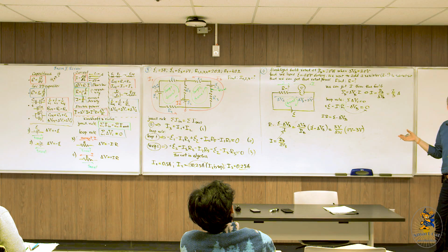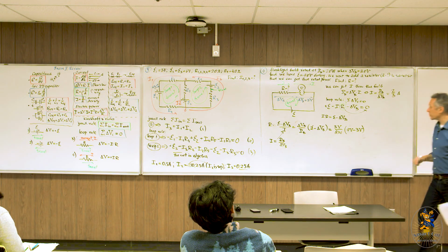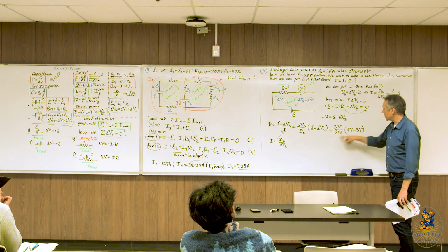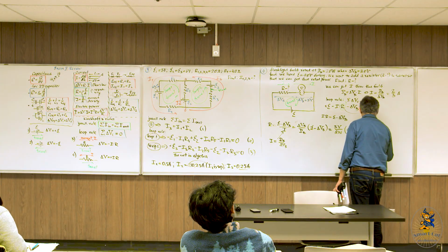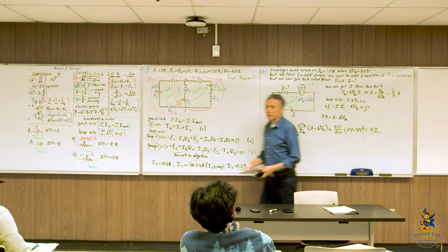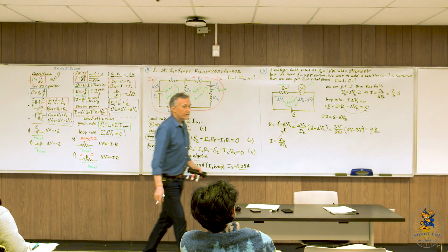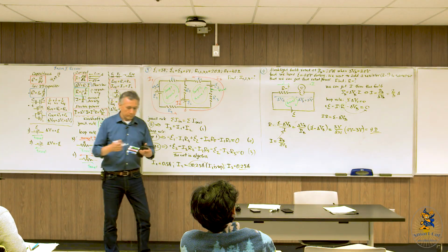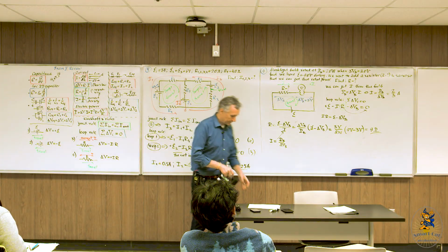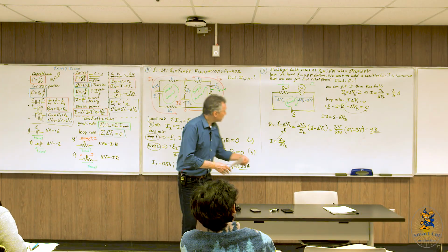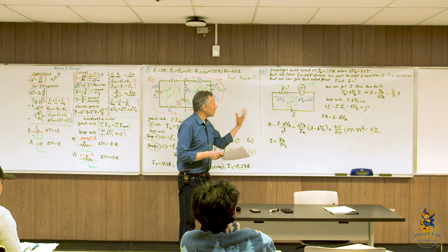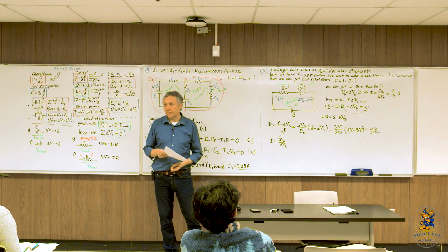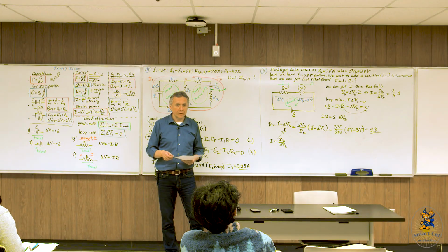It will be 9 ohms, 9 ohm resistor, right? So the 6, 3 times 3, 9. 9 ohm resistor. So you need to connect in series 9 ohm resistor in order to drive this bulb properly. Because who knows, if you apply 9 volts directly, maybe you can just burn it, so damage the bulb, who knows.